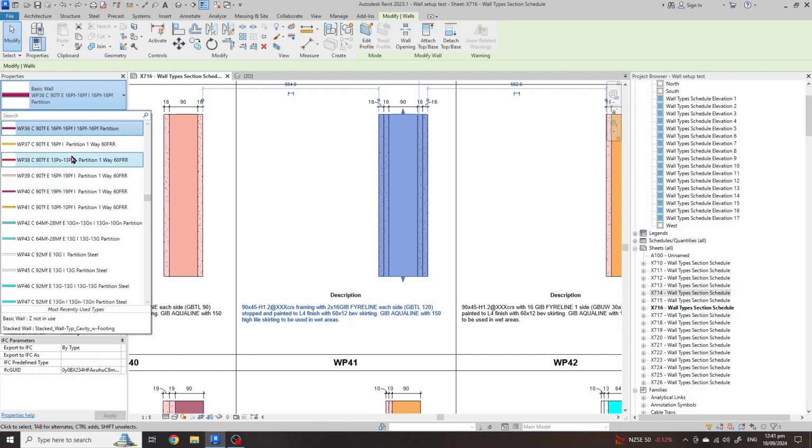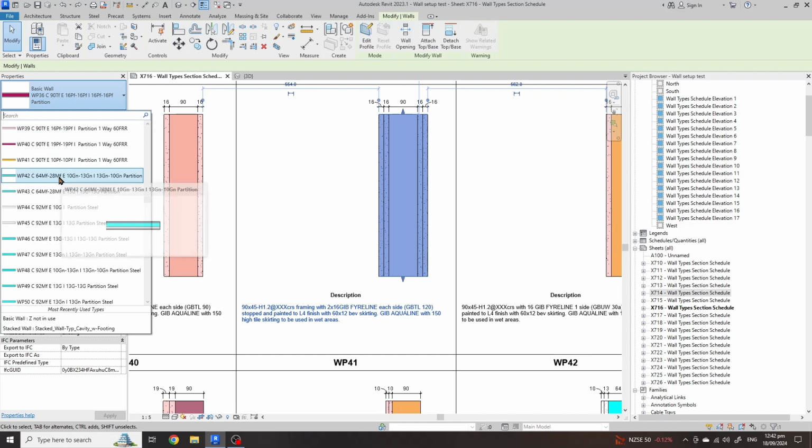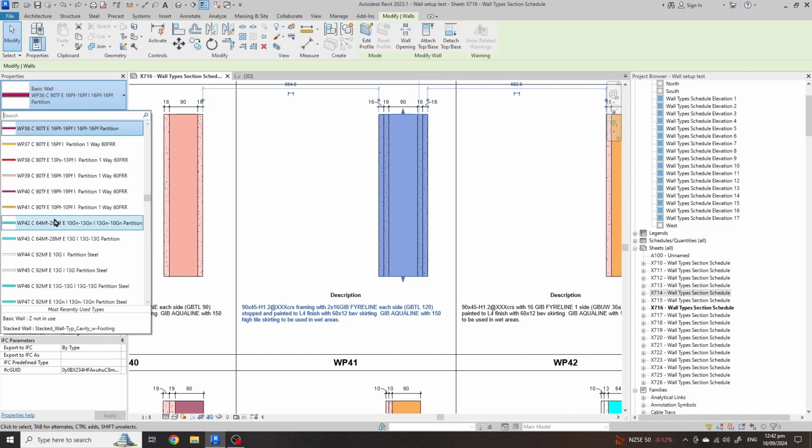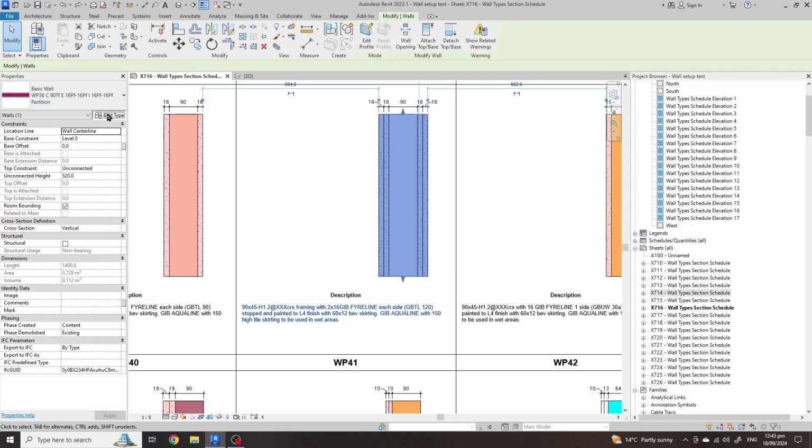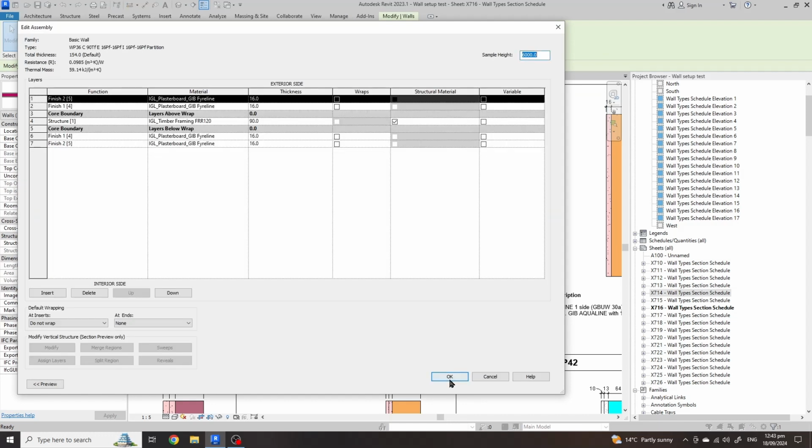After it's grouped them by that wall type assembly, then it'll order them by the thickness of the core. So after it's put the type mark and the type name, it does the wall build-up. So we've got C for core, E for exterior, and I for interior. And that's grabbing all this information from here. So it's pulling from the thickness here to put in that input. And then it's using an acronym in the material itself.